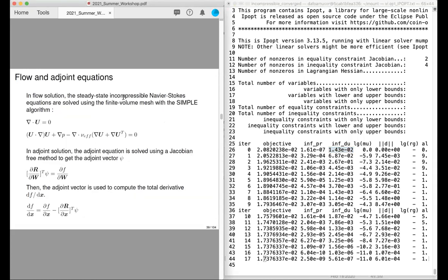Next, I'm going to talk about more details about the log files. But before that, I want to very briefly mention what equations we are solving. For this case, we are using the so-called simpleFoam, which is an incompressible flow solver that solves the incompressible version of the NS equation. It's a steady state simulation. In the adjoint solution, we are actually solving two sets of equations.